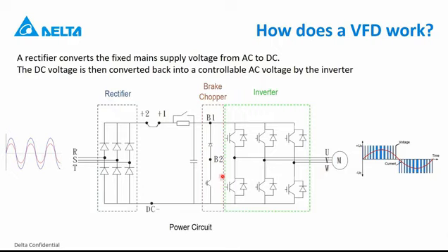And for the output phase loss, this is very easy to do. There's no software required or anything, because you have output current detection, so the drive can see the current going through each phase. And if one of the phases has absolutely no current, or there's some significant current imbalance, then the drive can just detect that. Okay, so I hope that clarifies it.